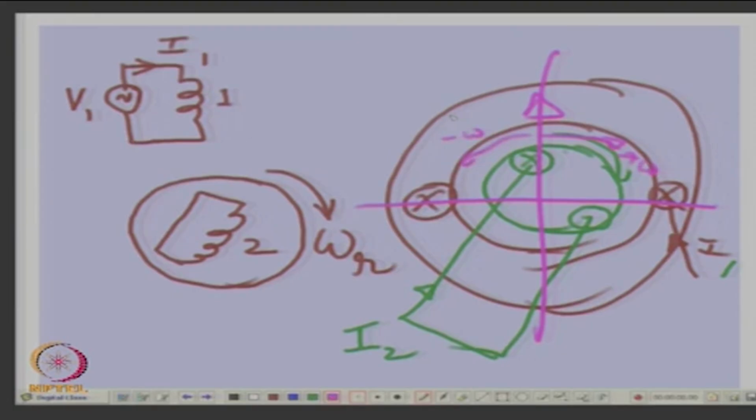Two rotating fields it will produce in the air gap, and these two fields will in turn induce a voltage in the windings which will oppose. Now, that will induce a current in the rotor also. And what frequency, you should be clear. If it is held stationary, it will induce the same as the supply frequency. If the rotor is stationary, it is like a transformer, is not it? So, it will have the same thing.